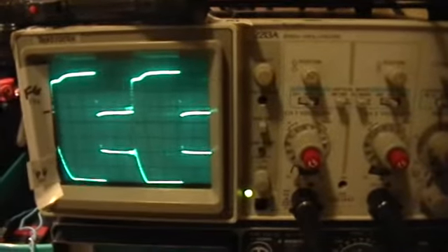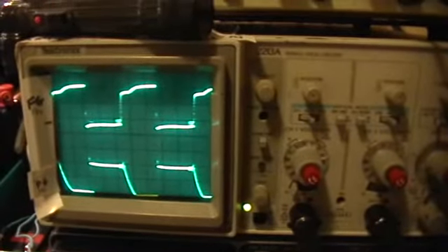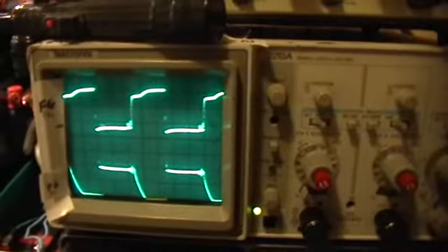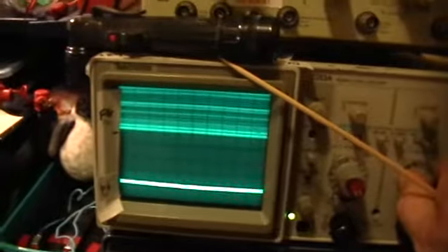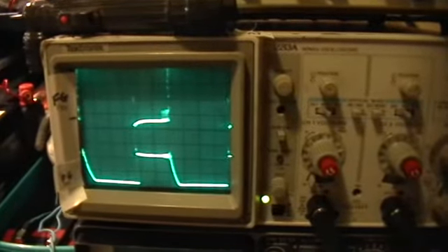As I change the duty cycle of the timer and get into that region where the scope loses trigger on that, there are your characteristic bands of lost trigger. And of course, if I magnify the volts per division, it looks just like what Aaron was showing. Okay, now that was the 555 timer trace. There's the MOSFET trace there.